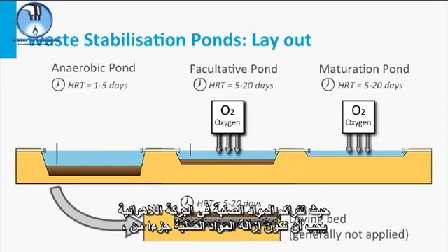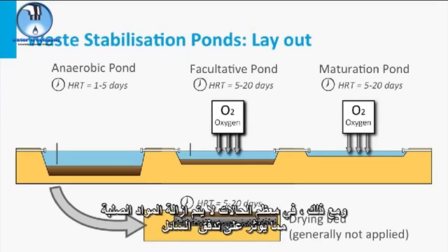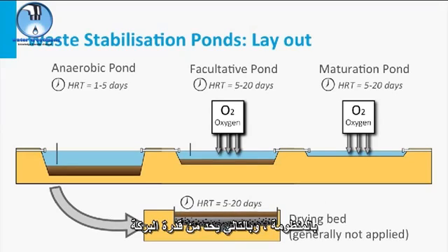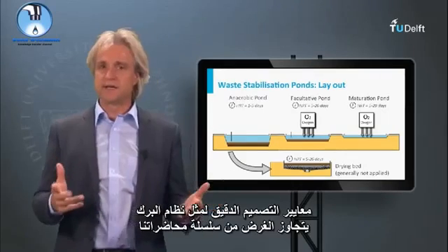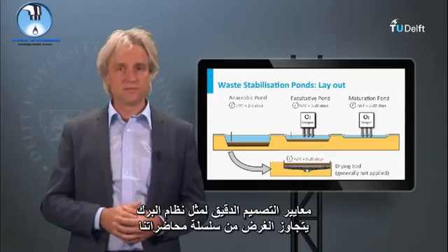Since the solids accumulate in the anaerobic pond, solids removal should be part of the standard operating procedure of pond systems. However, in by far most cases, solids are not removed, eventually impacting the liquid flow regime and thus reducing the pond capacity. The exact design criteria of such pond systems go beyond the purpose of our lecture series.